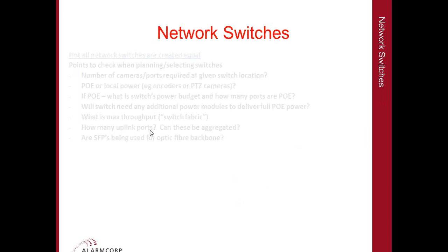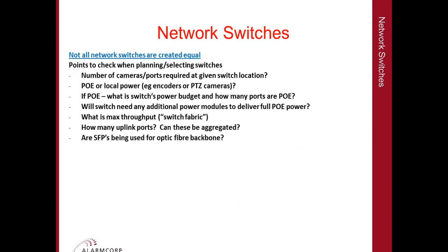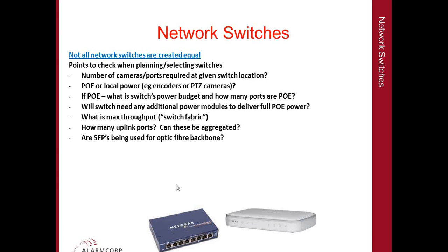Okay, a little bit on network switches. Not all network switches are created equal. Obviously, we have to look at the number of cameras or camera ports required at each given switch location. Now, PoE or local power, encoders or PTZ cameras. If we have a PoE switch, what is the switch's PoE budget and how many ports are actually PoE? You may find that on some smaller switches, you might have an 8-port switch, but only 4 of the ports are PoE capable. The rest are not.